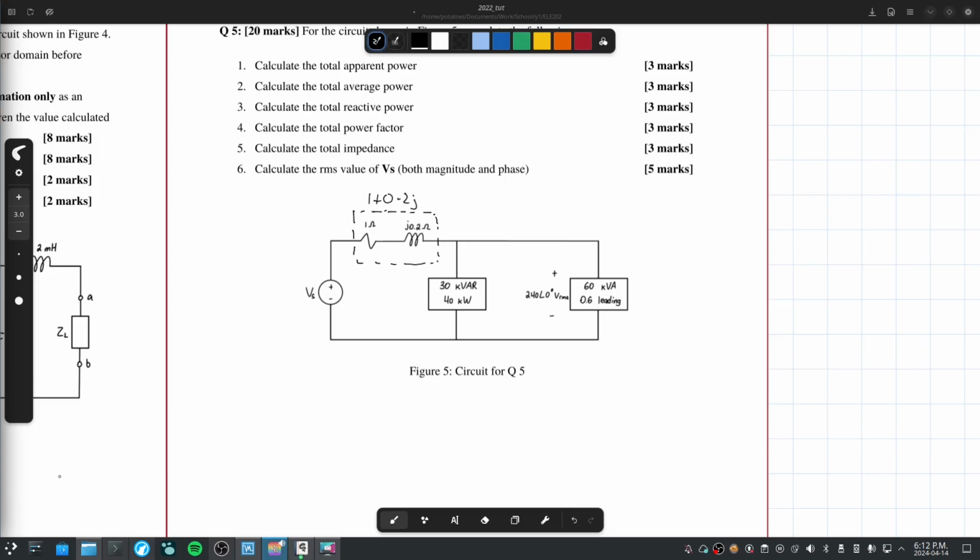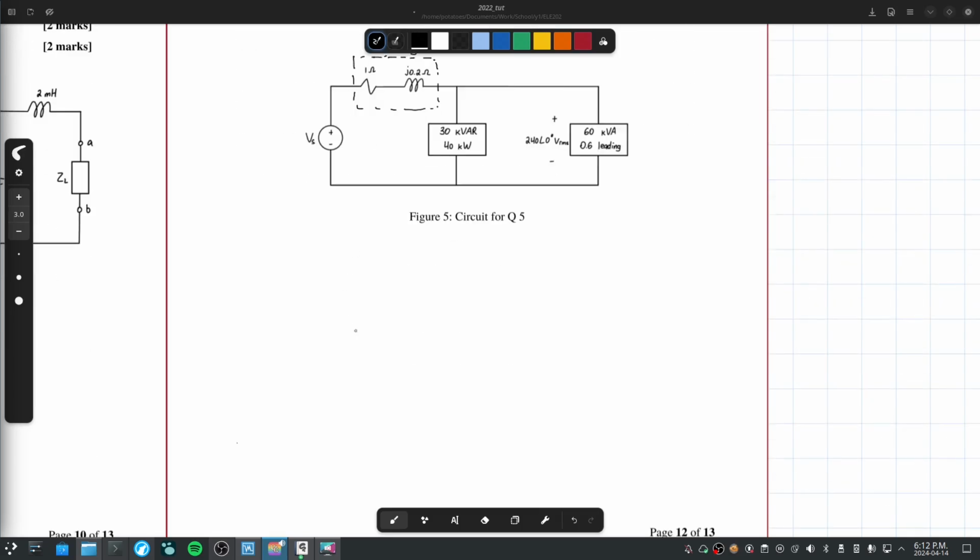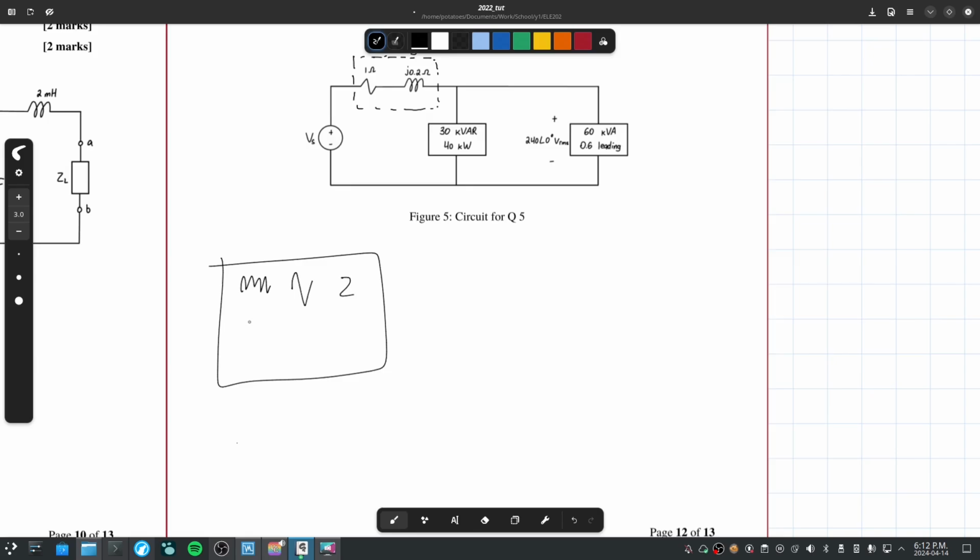You missed nothing. The series and parallel impedance works the same way as resistors. Inductors, resistors, and impedance all work the same. That is, you add in series, and in parallel you do 1 over the first plus 1 over the other, all to the power of -1. Capacitors is the other way around. That's it, pretty much.